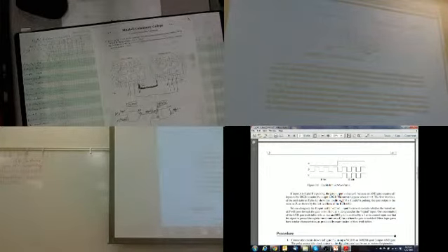Here, the blue one on the output, and then you have to turn the channel on because these other 3 channels by default will turn off when you hit the default setup button. Default setup makes it so that someone previous to you didn't leave weird settings in there, so it just clears all that information out. You just hit the blue button to turn on the blue probe. Just hit it one time and that's it. If you want to get rid of that menu bar, just hit menu off.